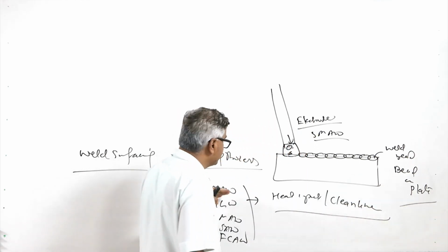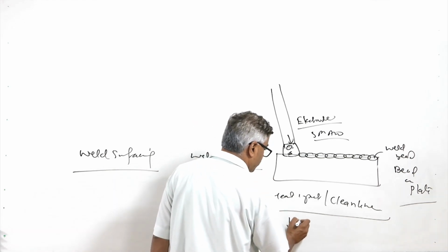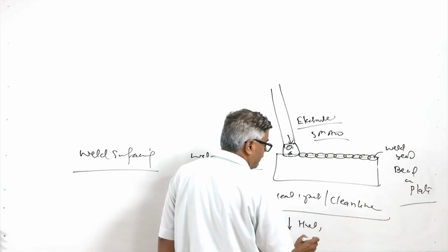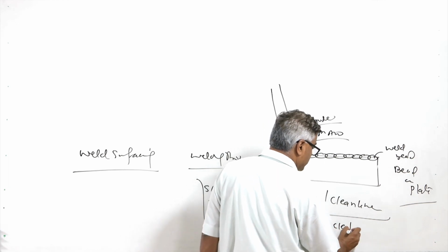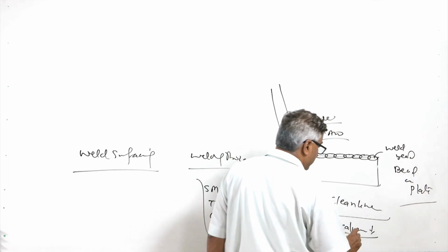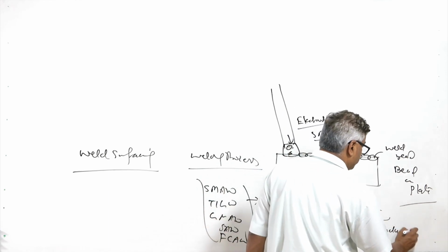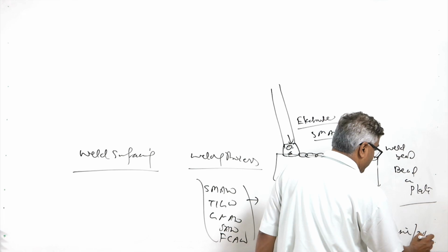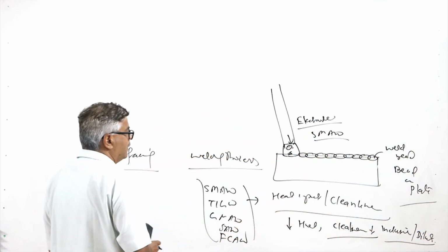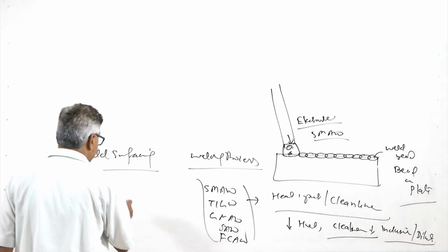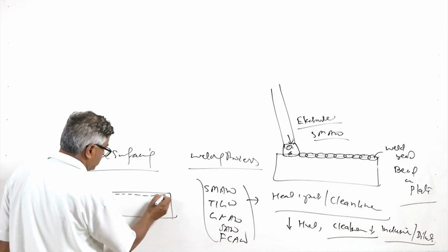The weld surfacing deposited using SMAW has less control over the heat input, and the cleanliness of the weld is also less. Because of this, we will have more inclusions and higher dilution levels, because control over the heat input is limited.